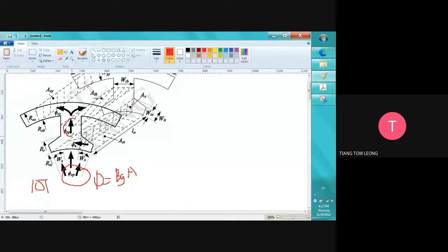So when it comes to here, we will assume 10 Tesla as well. It will not go anywhere. Principle of conservation of energy: how much flux do we have here? How much flux will go through here? So we know that this is BG, because we took BG, the magnetic flux density in the middle of the air gap. Then the area is the area of the stator pole.